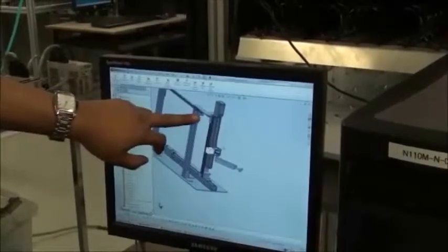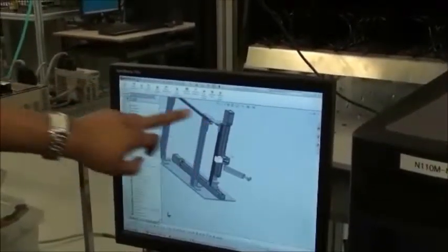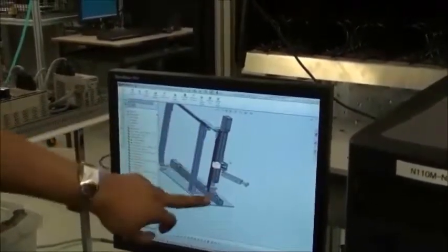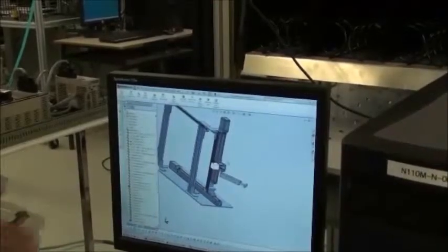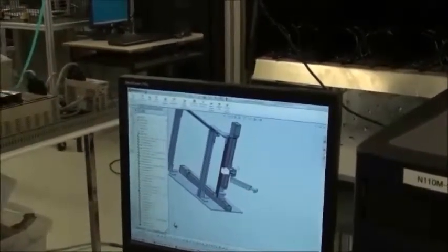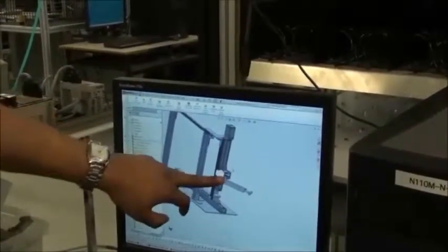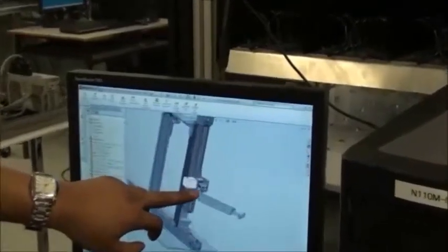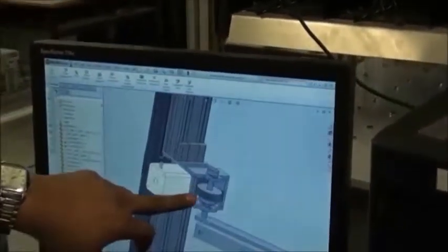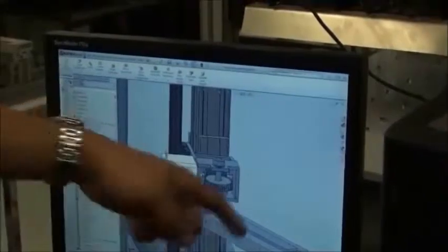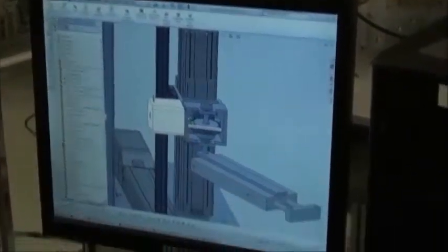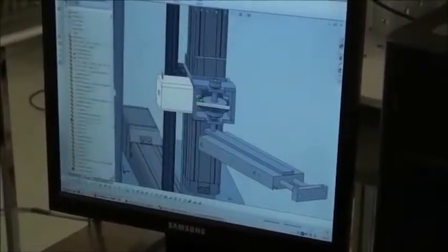So what we had to do was add stabilization systems horizontally and vertically to support the robo cylinders, because they're not strong enough to be able to do what we needed to do. And we also added a gear system inside for the motor, so that it gets better torque and it can actually turn the gripper without much effort.